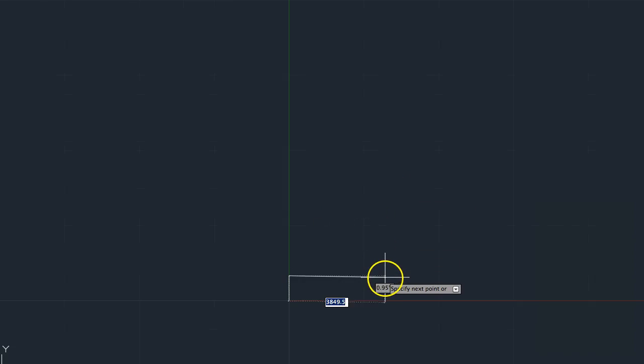AutoCAD is unusual in the way it references the coordinates. 90 degrees is anti-clockwise from 0 and so on. In the square I am drawing, the commands are as follows. The line goes from 0,0 to @1000 at an angle of 90, then @1000 at an angle of 0, @1000 at an angle of 270, and finally @1000 at an angle of 180. I'm not sure why they chose to do the angles the way they did, it's just AutoCAD convention.